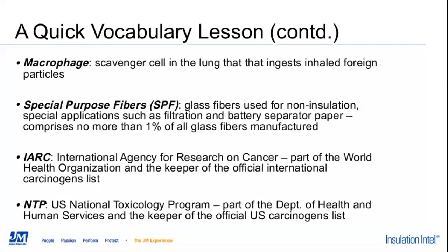You have a special purpose fiber, SPF, and these are glass fibers used for non-insulation special applications. They're not very common. They're in about 1% of all glass fibers manufactured. They're used for things like filtration and battery separator paper. These are not fibers that the general public can buy. They're used in highly, highly specific applications.